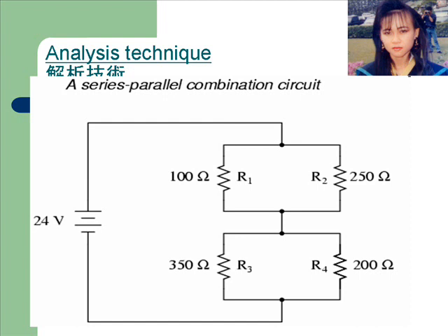Step 7: Repeat steps 5 and 6 until all values for voltage and current are known in the original circuit configuration. Essentially, you will proceed step by step from the simplified version of the circuit back into its original, complex form, plugging in values of voltage and current where appropriate, until all values are known. Step 8: Calculate power dissipations from known voltage, current, and/or resistance values.